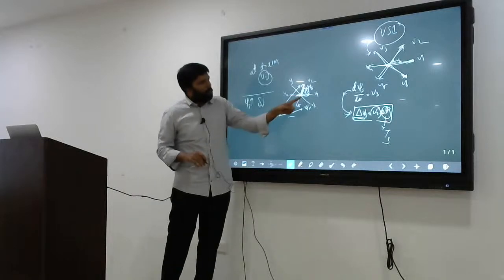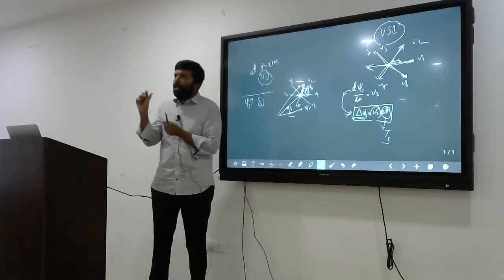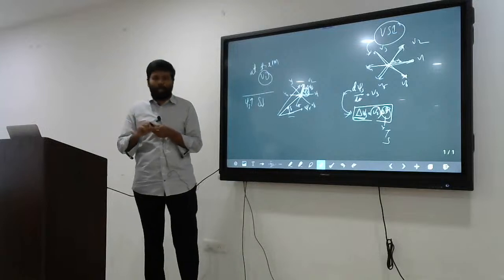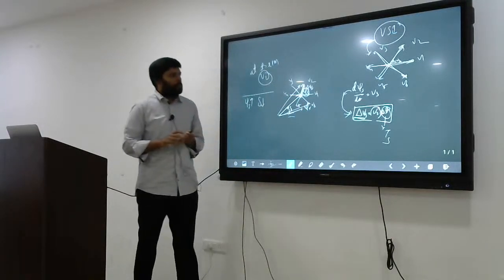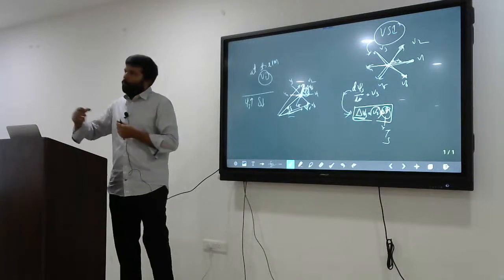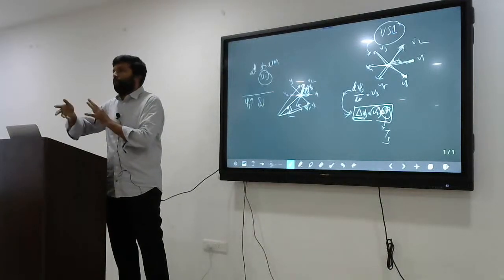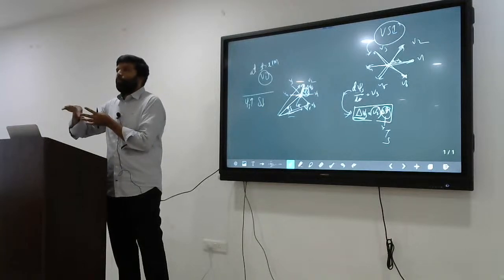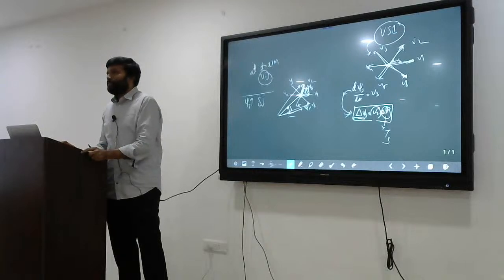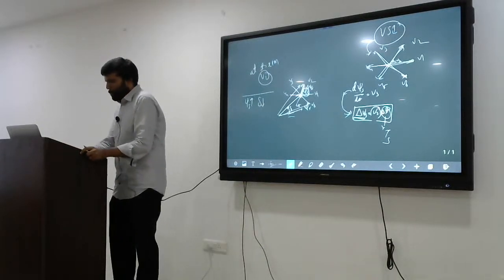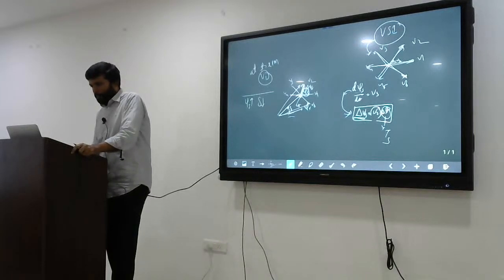V1? No. If you take V1, what will happen? Change in load angle is very less. Instead of V1, if you select V6, what will happen? If you select V6, flux increases, and change in delta is also more. Compared to V1, if you select V6, change in delta is more, so the decrease in torque is more. Understood? Clear? Give me 1 minute. I will try to explain using different phasor diagrams so that you will understand this concept.